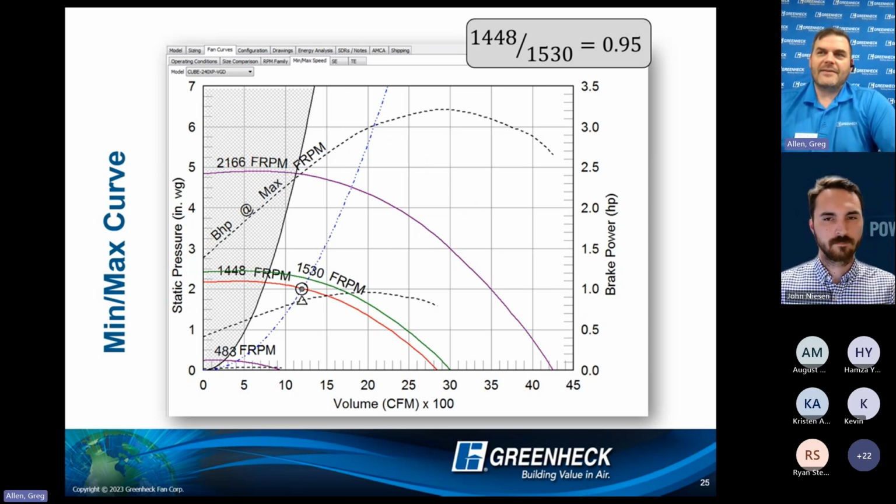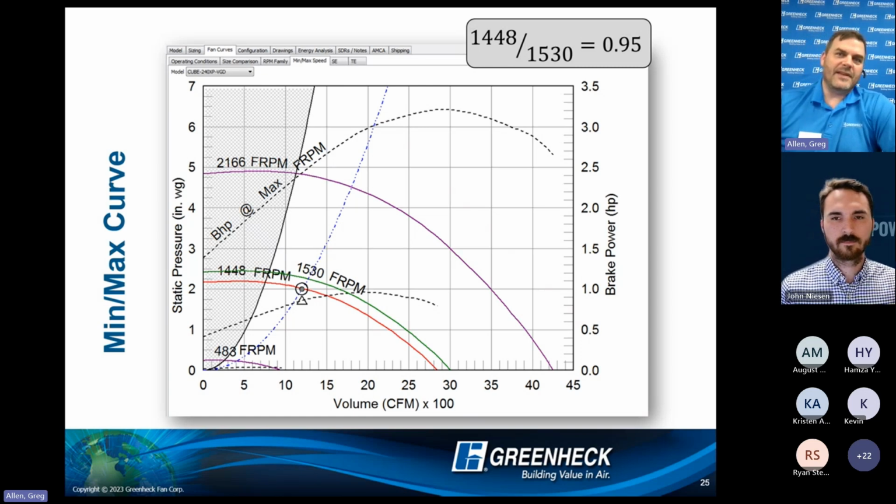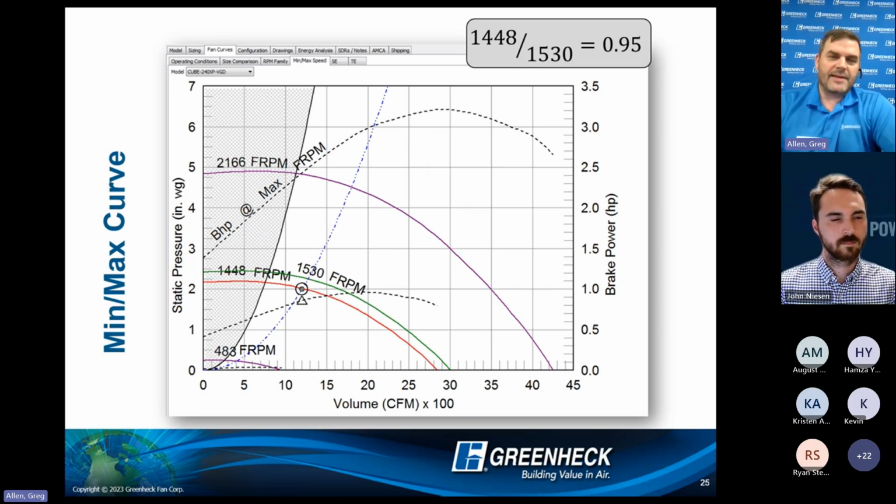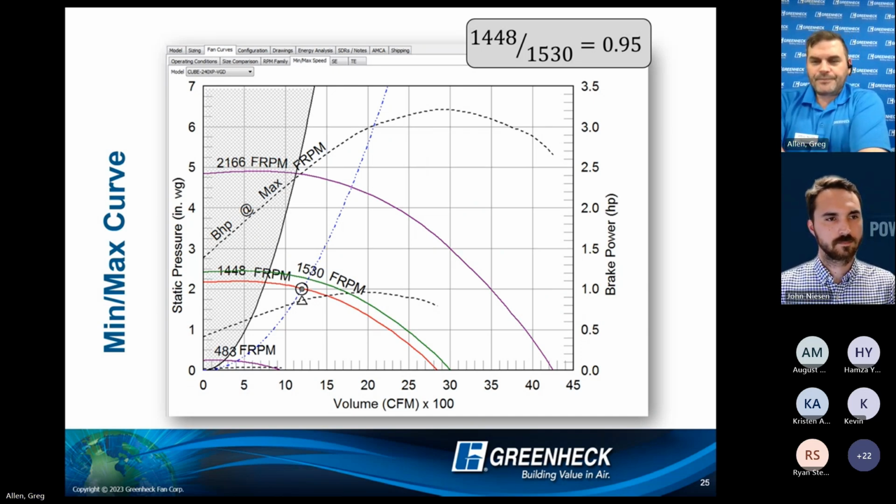It's very common with EC motor fans. You might find a 1250 RPM max condition. It's not because the motor can only go 1250. It's because the manufacturer programmed it to stop at 1250 because that's where you run out of horsepower. The same motor in a smaller fan might allow 1725 RPM. That is represented by 10. So wherever your max programmed is represents full speed.